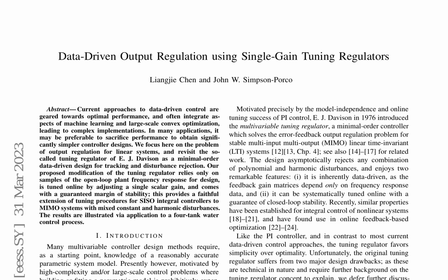demonstrate in subsequent sections. A novel approach to designing a single-gain tuning regulator for low-gain stabilizable systems is presented, comprising a 3-step implementation procedure. The methodology begins with the definition of the SSLG operator L, a linear map utilized to solve for the desired feedback gain matrix F. This is achieved through eigendecomposition of the system matrix and application of the final value theorem from Laplace transform theory, yielding an expression for L, F, involving a sum over residues at the poles of the system's transfer function and